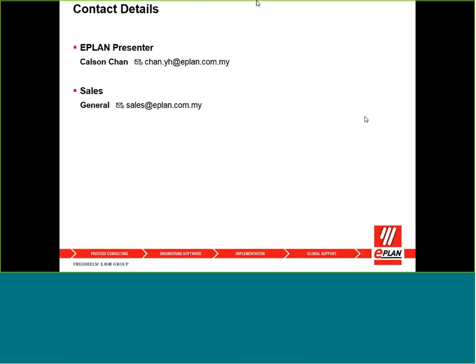And then the next question will be, can we auto wire number the schematic diagram? Yeah, of course. We have one function that you can actually use for automatic wire numbering of the schematic diagram in the EPLAN software. Okay, just by one click of a button, they will run the counter by itself. And of course, you can create your own format according to your company standard. And then there will be an auto wire numbering format. So just one click of a button, you can run it.